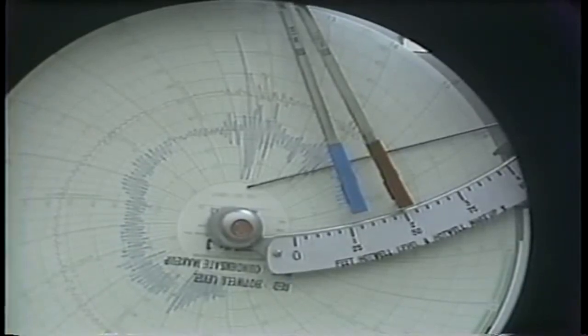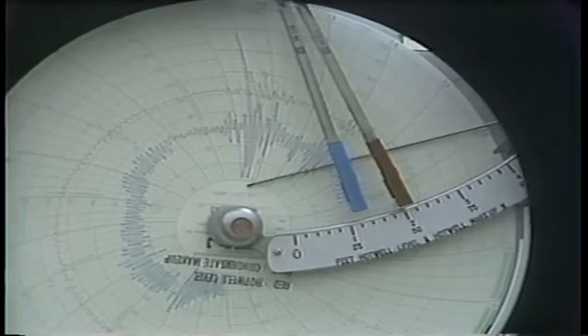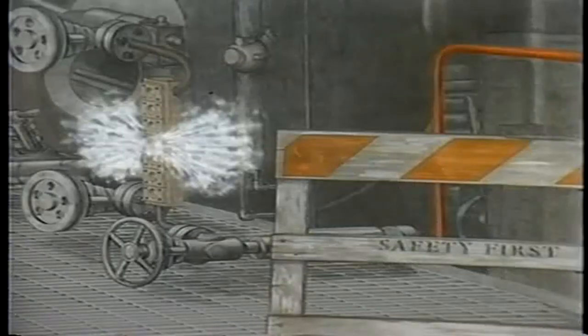The boiler can then continue operating until it is convenient to schedule a shutdown. This being the case, the operator must isolate the area around the leaking gauge glass and inform supervisory personnel of this abnormal condition and the need to schedule the unit offline. If neither of these choices are possible, then the operator must take the unit offline immediately.